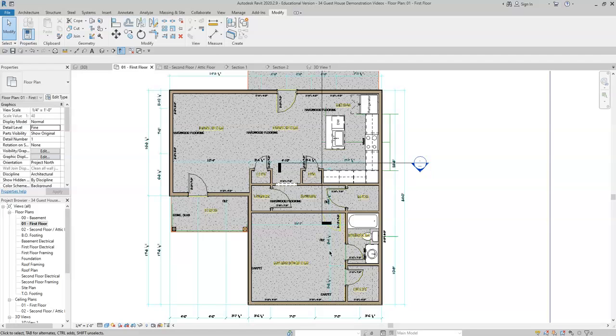Once we have placed our plumbing, appliances, and cabinets in our house, we will move forward by placing windows throughout the exterior of the home. Now we wait until this moment to place windows in our home because our windows are going to be placed around things like your kitchen cabinets and your bathroom fixtures, mainly above the toilet or a shower. So we wanted to have those in place first before we placed the windows in.